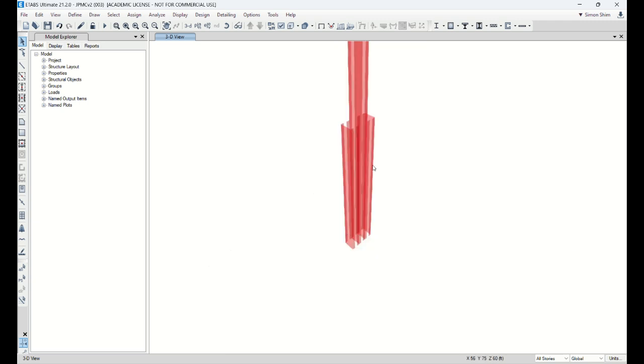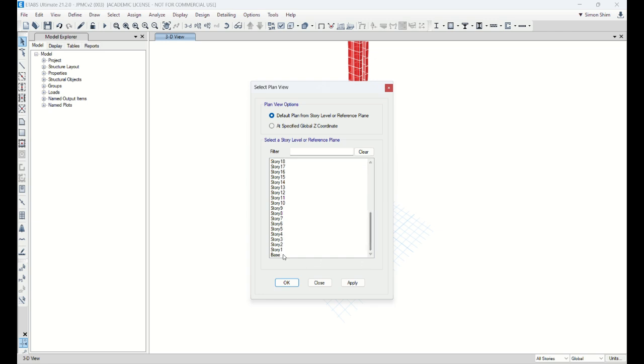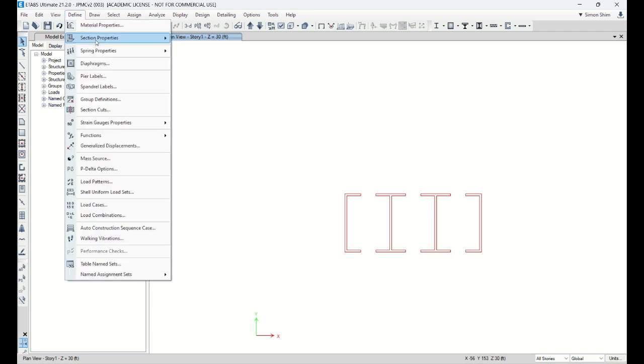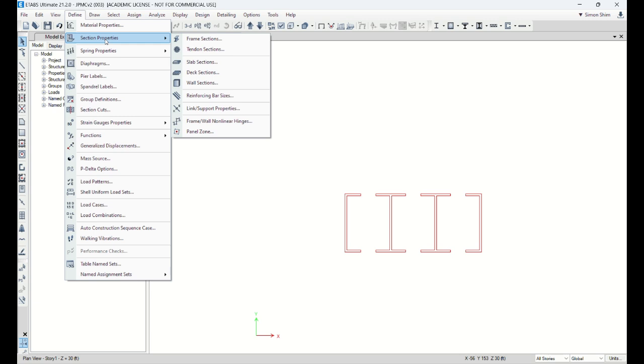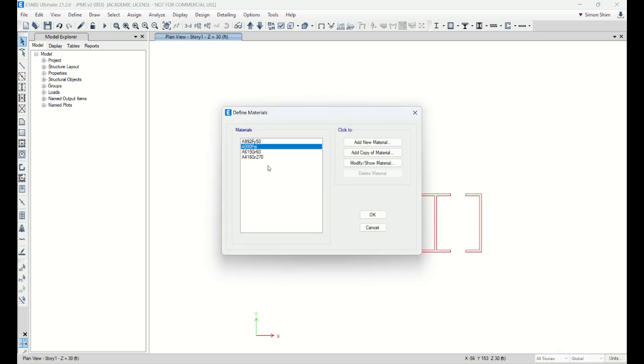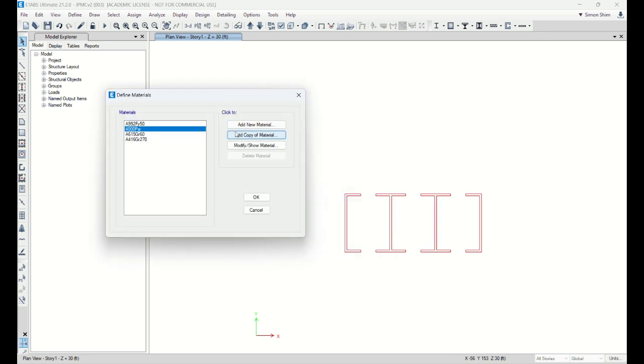But now, since the wall is segmented and subdivided, we need to brace it. What that means is we need to provide coupling beams here. At this point we haven't set up the wall sections, so now it's time to set up the wall sections with various thicknesses and concrete strengths. Let's see what we have. First of all, by default we have only 4,000 psi concrete, and we need to use high-strength concrete, right?